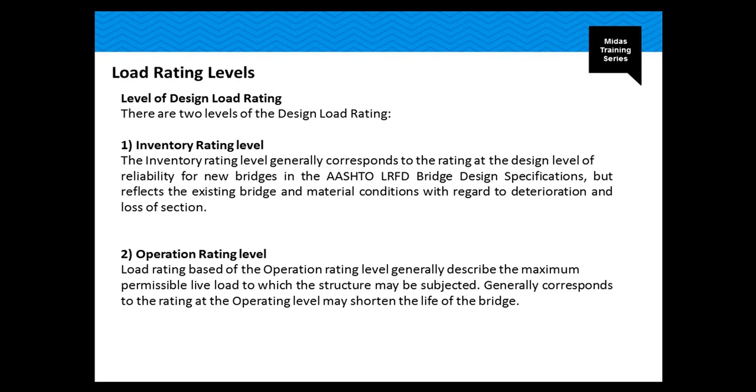This is why the inspection is so necessary to perform the bridge load rating. And then we have the operating rating level, which generally describes the maximum permissible live load to which the structure may be subjected. Generally, a rating at the operating level may shorten the life of a bridge.